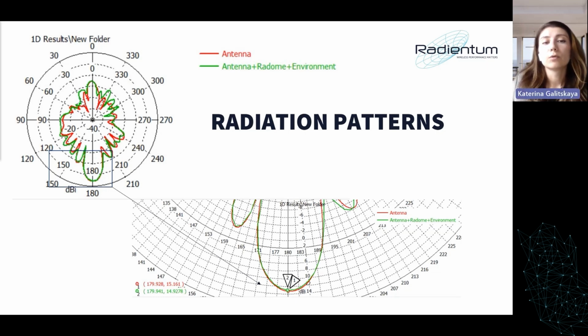And that's also very useful when performing tolerance analysis, because on these frequencies, as you can think, tolerances affect a lot. Thickness of dielectric for printed antennas, again, tolerances in your radome, that all will affect the final results a lot. What you actually get in real life may not match your simulation, because if you just simulated some perfect case scenario without taking into account any tolerances, then probably it won't be the same.